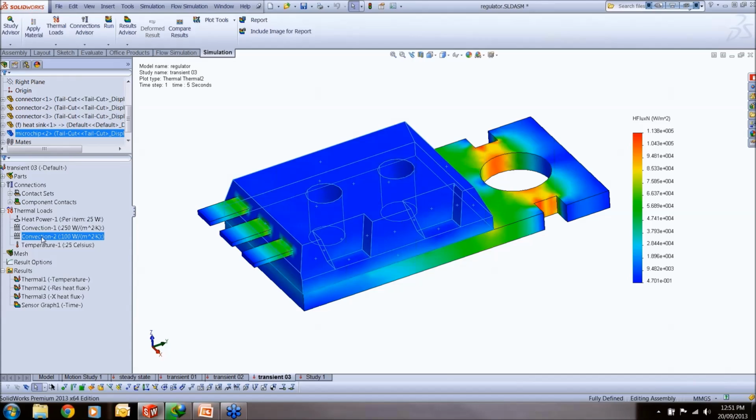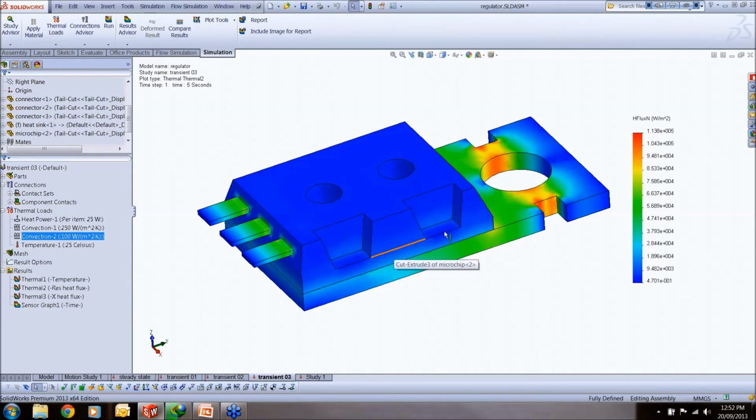This is not a real case, and if your case study is concerned about a very detailed and accurate measurement of this, you have to take your model, put it in, let's say, a flow channel, where it could be a zero velocity flow channel or a forced convection case, and do the thermal analysis in a flow simulation, get the temperature distribution over the whole phases there, and bring it to this study.